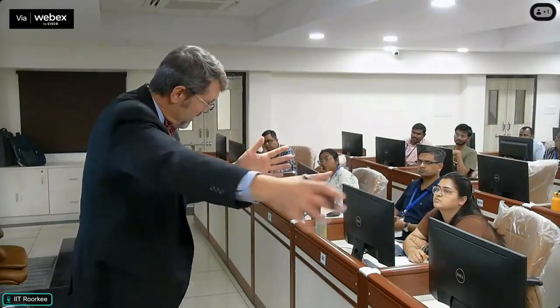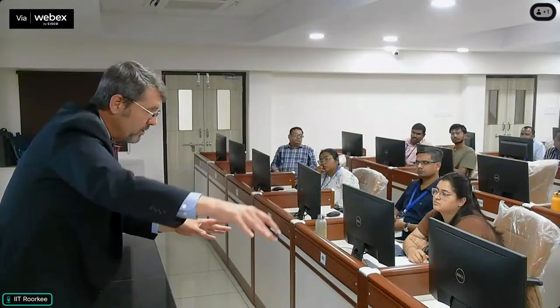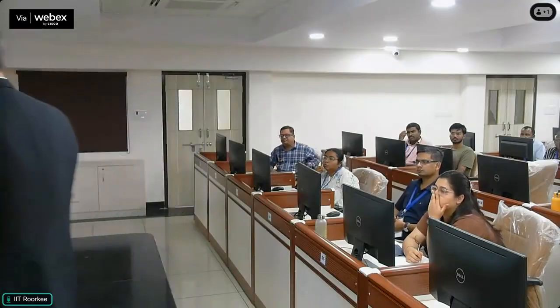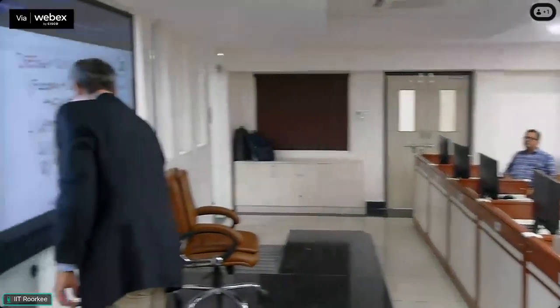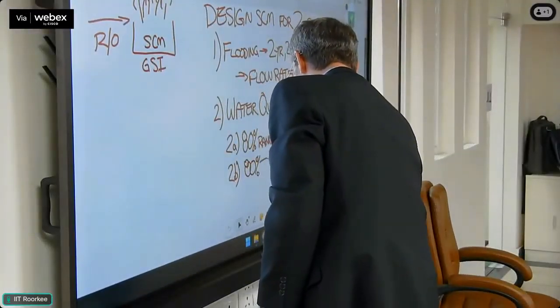Part two, 30 millimeters to 25 millimeters of whatever storm, all the storms that exceed it. And then part three is the bypass, the value of all the bypass above that threshold. You add all those up, combine them, the amount that's treated should be 80% of treatment. All right, so I'm going to call this, instead of 80% ranked, we're doing 80% treated.